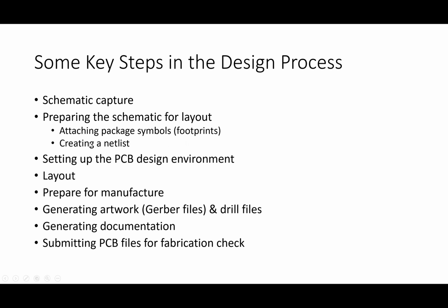And then creating a netlist, which is an important element of the manufacturing process. This netlist basically creates for us a list of all the nodes in the circuit and tells us where all the nodes are connected. Then he goes through setting up the PCB design environment, essentially creating some basic standards that he's going to use. So things like what basic line widths should be, what the vias are going to be. We're going to talk a lot more about this later on in the semester. We're just getting introduced to it right now, but we're going to talk a little bit about why we have some of those constraints.